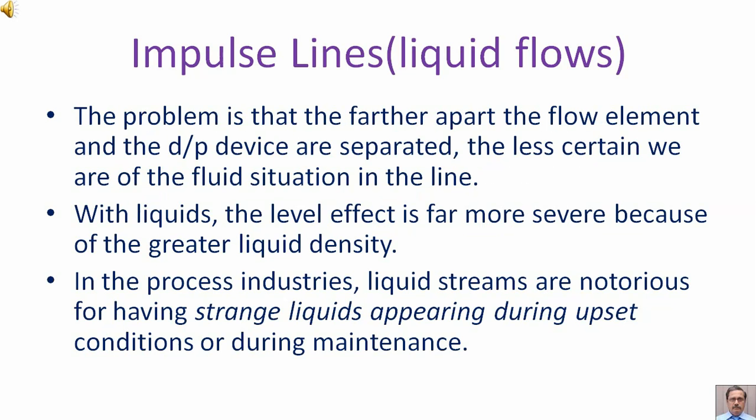Impulse lines for liquid flow services. The problem is that the farther apart the flow element and the DP device are separated, the less certain we are of the fluid situation in the line.